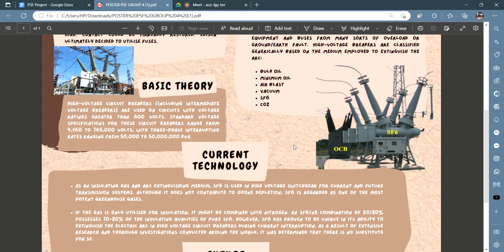Oil circuit breakers (OCB) are circuit breakers with oil immersed contacts. The current interruption occurs in oil, which cools the arc and so quenches it. Small oil circuit breakers have their poles in the same oil tank, whereas huge high voltage circuit breakers have each pole in its own oil tank. Normally, the oil tanks in oil circuit breakers are sealed. Porcelain bushings are used to make electrical connection between the contacts and external circuits. Then we go to Reza.